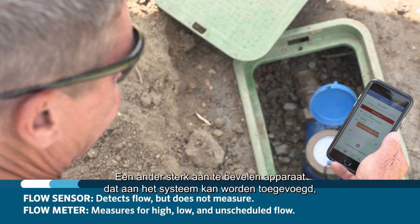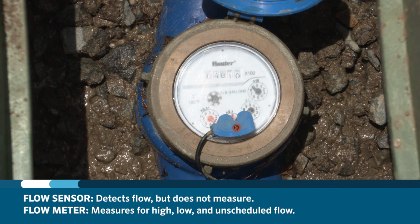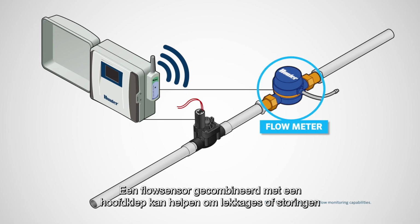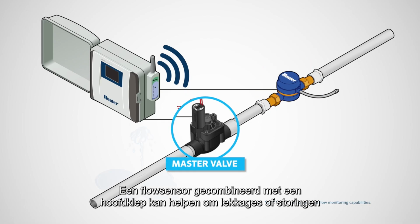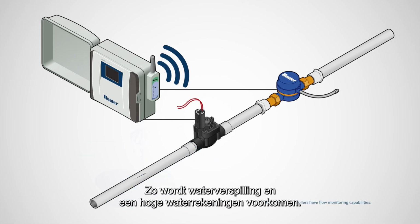Another highly recommended device, known as a flow sensor or flow meter, may be added to the system to monitor for high, low, and unscheduled flow. A flow sensor or flow meter, in combination with a master valve, can help to identify failures in the piping system and shut down the system, preventing water waste and high water bills.